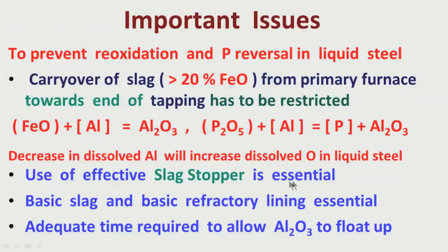So, when liquid steel is getting tapped, whenever slag tries to come near the tap hole, the dart will come to the tap hole and stop the slag from coming through it. So, this is a way it can be stopped, or to some extent controlled.